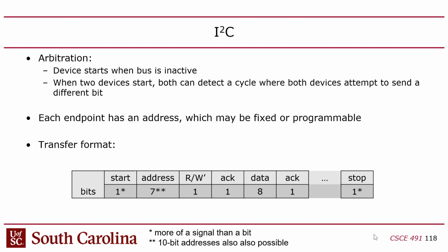Okay, now the start bit and the address are going to be set on the bus by the master. Whoever's taking mastership of the bus will put out the start bit and the address, and then a read or write flag, which is much like SPI, that it has to indicate whether it wants to read or write. Okay, now this is where things get a little crazy because at that point, the master releases the data line.